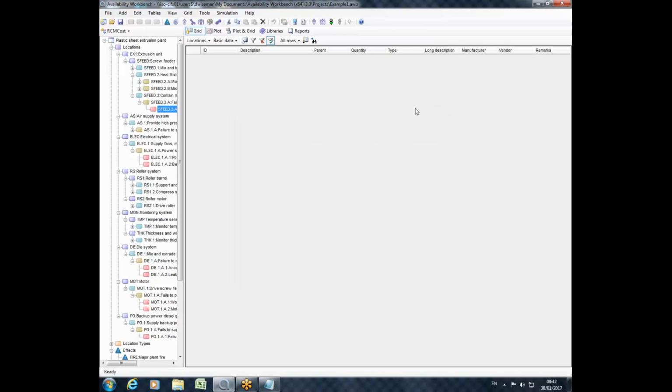So we've built our hierarchy, we've populated it with failure data, with maintenance data, and we've specified the effects of failure as well. So now maybe we have enough information to start looking at improving our maintenance strategy a little bit. So there are a couple of ways to approach this. One is you may choose to optimize each individual task in your project. So all your tasks may be treated independently, and you want to modify each one to get the optimum cost from that task.